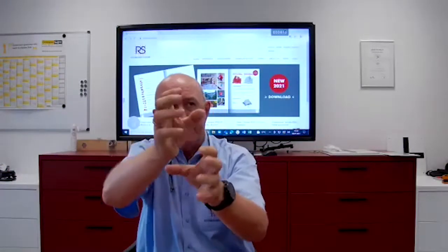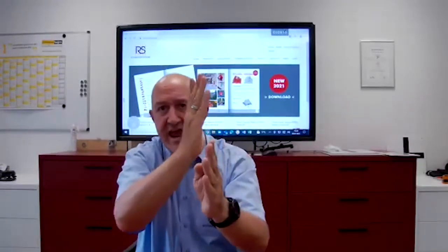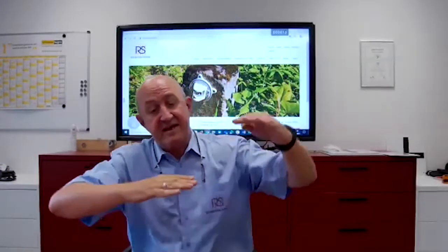Important is that when we monitor a building, we want to monitor on the top, not on the ground. In the past, we had these bolts, but in my opinion they already have an error, because it's not straight ahead, and you have to add the level very accurately. More important, in my opinion, is that we have a two or three step monitoring.